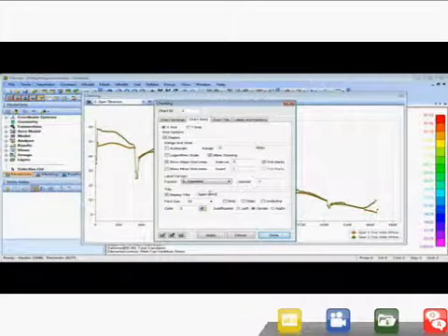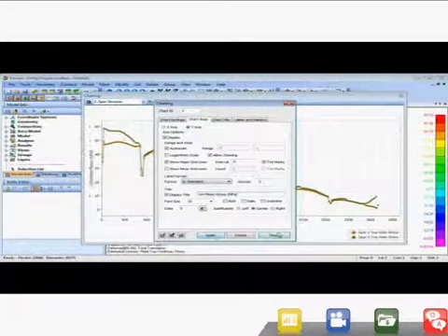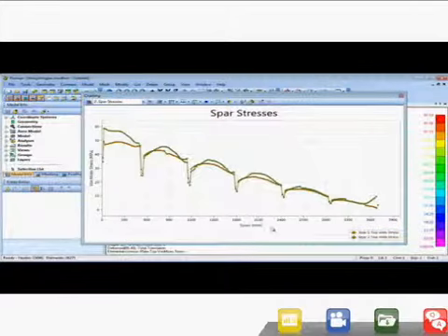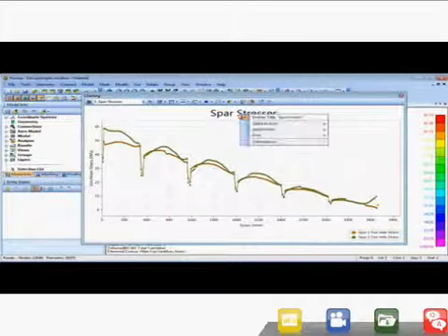The XY plots are based on a series of data taken from the analysis results, and can be filtered down to particular vectors or increment steps for nonlinear transient or frequency results, and displayed for regions or subcomponents of the model. You can set up different groups for different data series, and for incremental data you can set the desired beginning and ending output set.